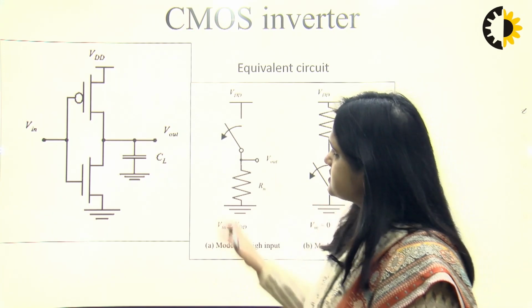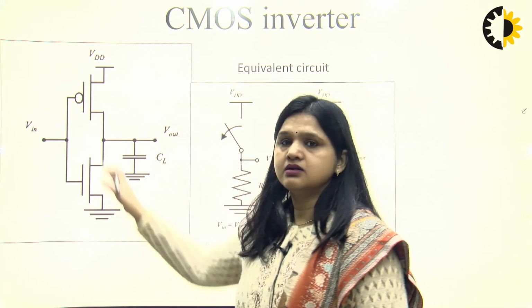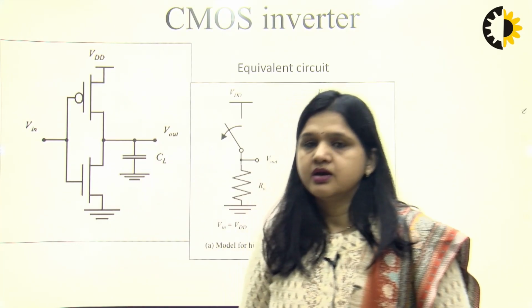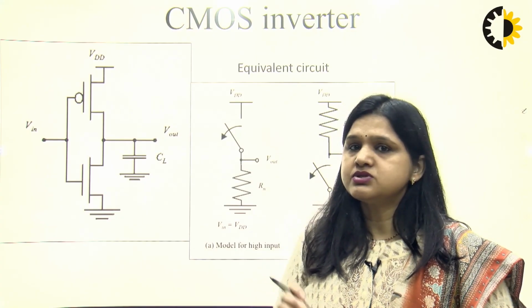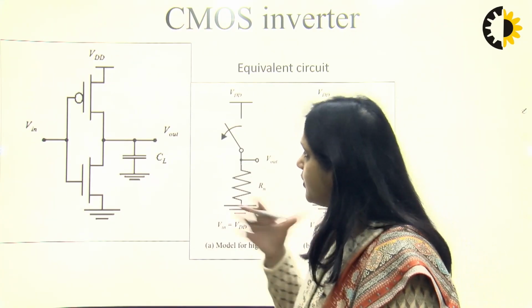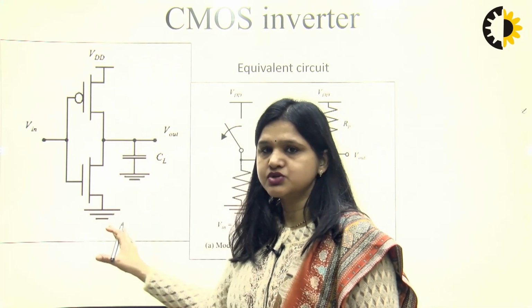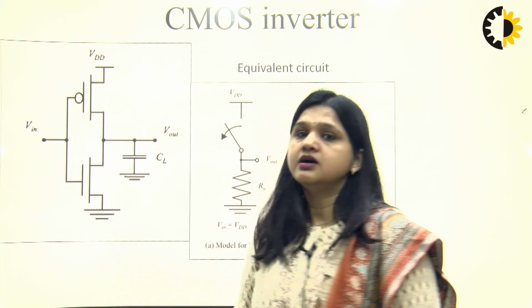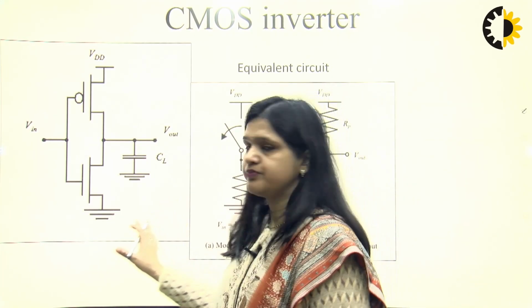A CMOS inverter is nothing but a combination of NMOS and PMOS technology. Nowadays CMOS technology is very popular in the field of VLSI design because of its low power consumption. In CMOS technology, the static power dissipation is zero.